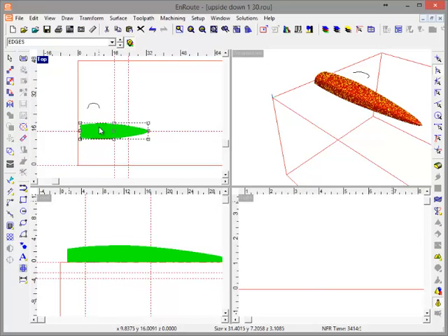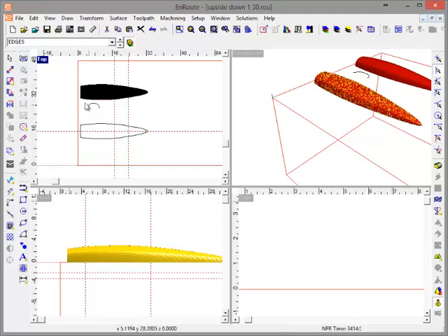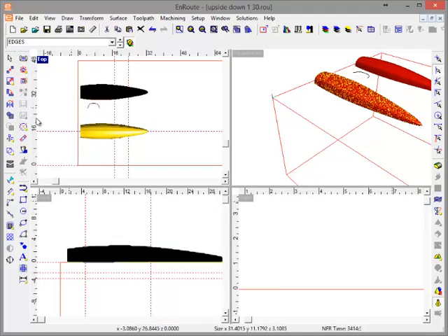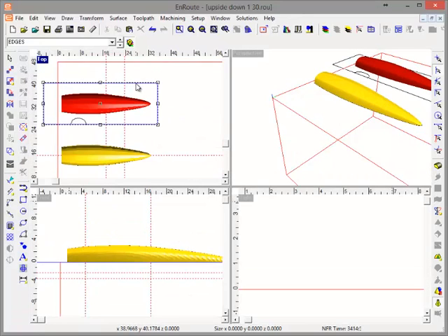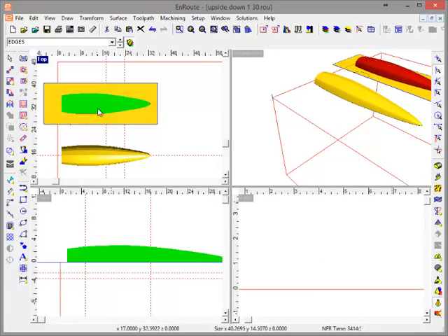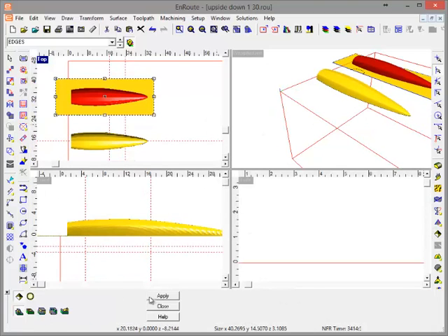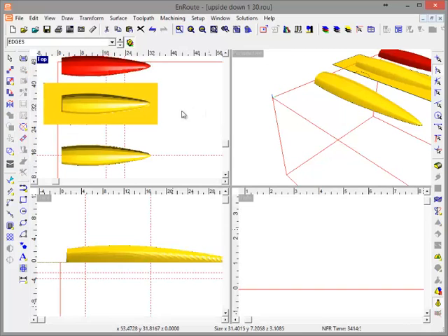If for whatever reason you wanted to not use those contours, which I can't imagine why you wouldn't, but there might be some reason for whatever, then you could just come here and make a flat relief. You can select your mesh and your flat relief and apply one to the other. And there you have your relief.